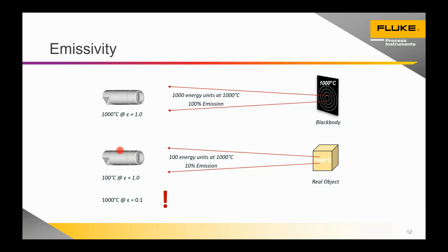I would say that 85–90% of devices that we receive for calibration, as long as the optics are clean, not scratched, and the sensor hasn't been overheated, never need to be adjusted. There's a very small consideration in a sensor's first year in terms of detector aging, but that's all taken care of in our standard accuracy specification.